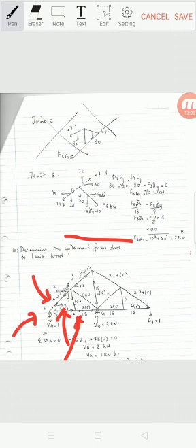As you can see at joint H, we have 2 kilonewton acting to that joint, and 2 kilonewton, and there's no force in the y direction. Therefore, the BH internal force becomes automatically 0. Since the force at H is 2 acting to point H, the GH force is also acting toward point H, which is 2 kilonewton.